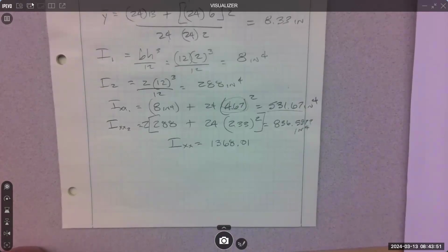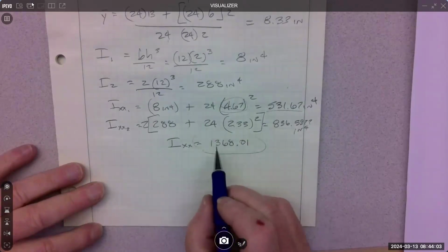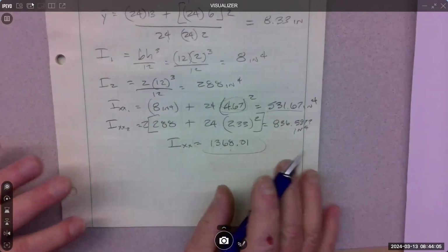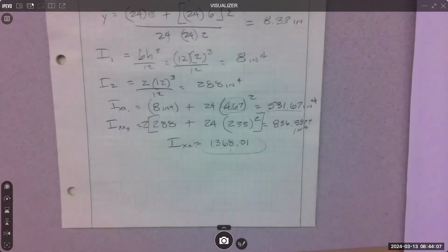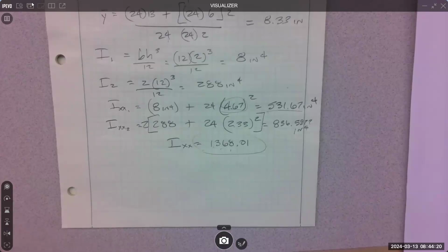We're good. In strength of materials, we'll be working with factors of safety of probably 3 and up. So rounding is okay, actually. We're gonna be able to say 1368 would be fine to use as your design parameter. Because in the end, if we're not within a factor of safety of 3, we're gonna toss it and start over anyway. Rounding becomes less important as we go through the numbers in strengths because we're always gonna be adding this factor of safety.